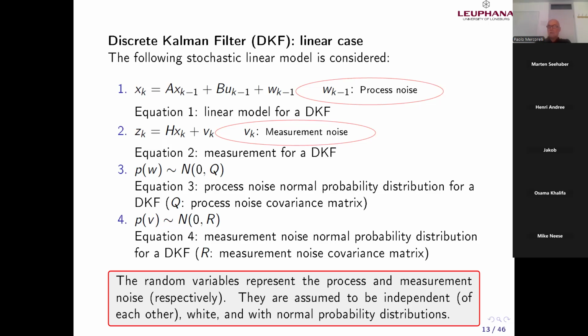The second equation characterizes the sensor. We can see exactly as before, instead of H, we introduced the matrix C with one row, two columns, and then we associated the measurement noise, the vector V of k, which is somewhat similar to W of k in its characteristics, but this is associated to the output, to the sensor level, and W is associated to the system, or to the state.